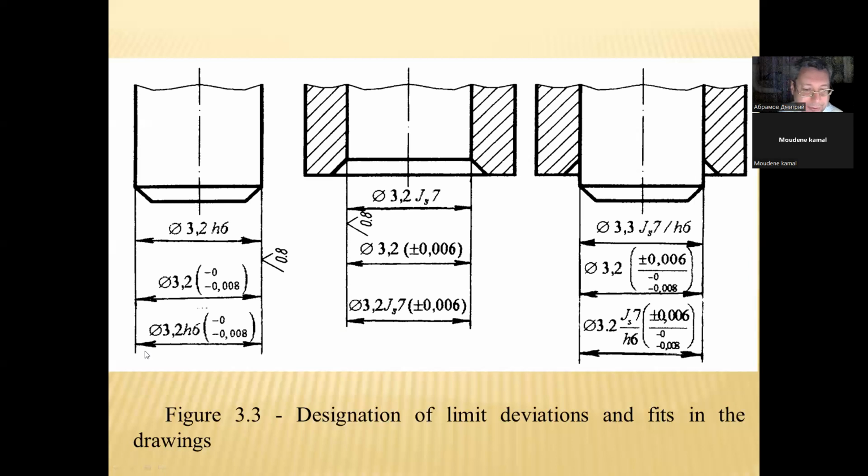And for the third designation of the dimension, we use both variants: fundamental deviation and IT grade, and limit deviations.